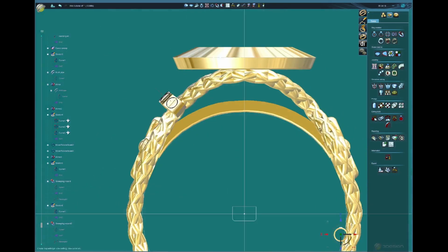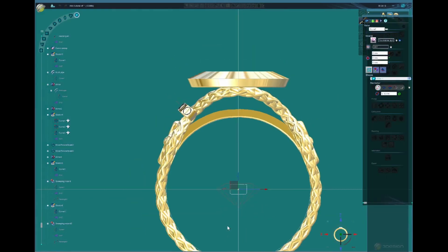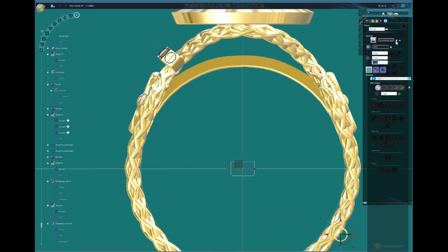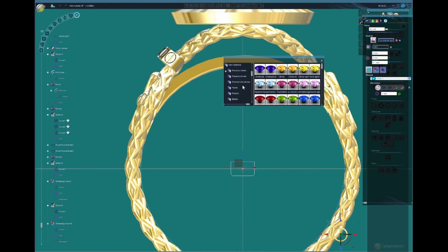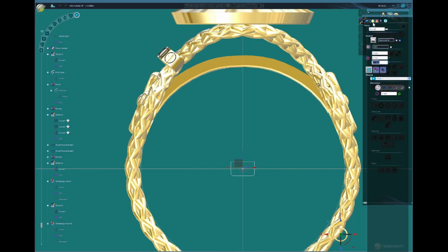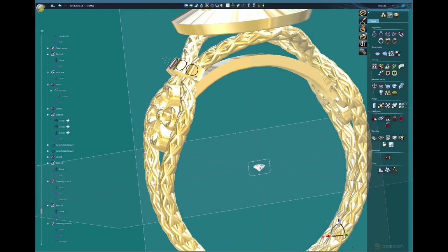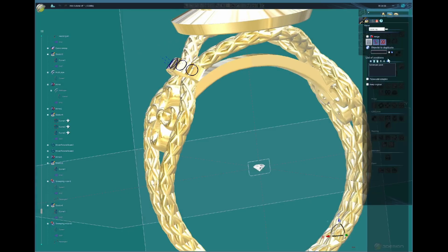We are going to get the stone. Let's make one especially for this one. And you're going to put up 0.10 millimeters. And that's going to be diamonds. All right, a little up from the plane. We click on pavé, jeweling, and click the stone.